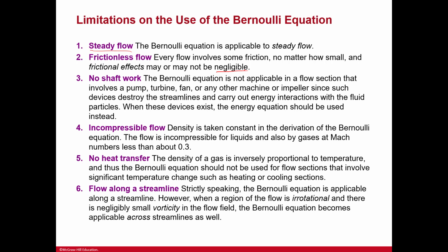No shaft work. The Bernoulli equation is not applicable in a flow section that involves a pump, turbine, or any other mechanical device. When such a device exists, the energy equation should be used instead. Incompressible flow: density is taken constant in the derivation of the Bernoulli equation, and the flow is incompressible for liquids and also gases at Mach numbers less than 0.3. And then no heat transfer.